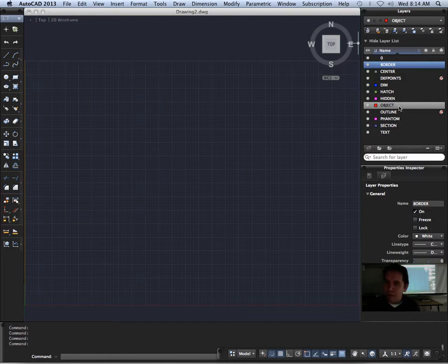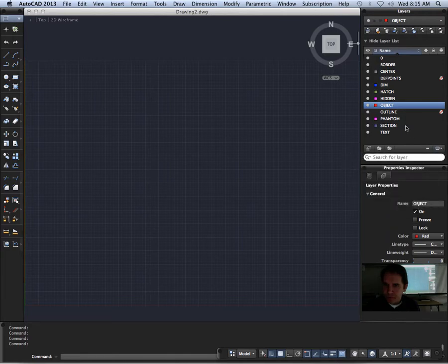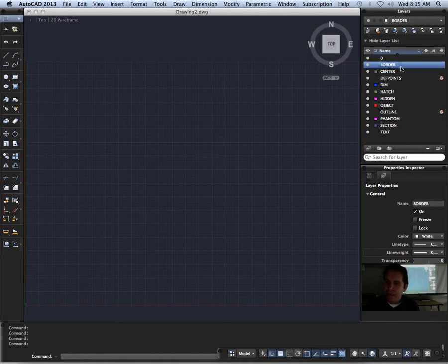And then in our border, so down here, once you've clicked on your border section here, underneath here it says the properties for this layer. And what we want to do here is go to our line weight, and we want to set our line weight to 0.3. So when we draw lines in our border layer, they're automatically going to have a little thicker weight to them, so they look nice. Okay, so I think that's all we need to do there.